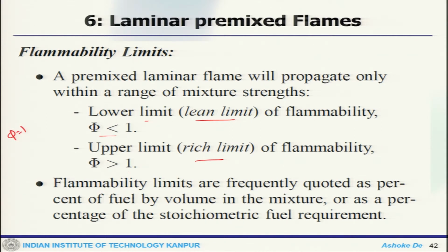Now, this is quite frequently quoted as percentage of fuel by volume in the mixture or as percentage of the stoichiometric fuel requirement. If you look at gasoline or diesel fuels at the petrol pump, you will see there is a limit they mention. So, any particular fuel has a flammability limit. Beyond this bound, a reaction is unlikely to happen.